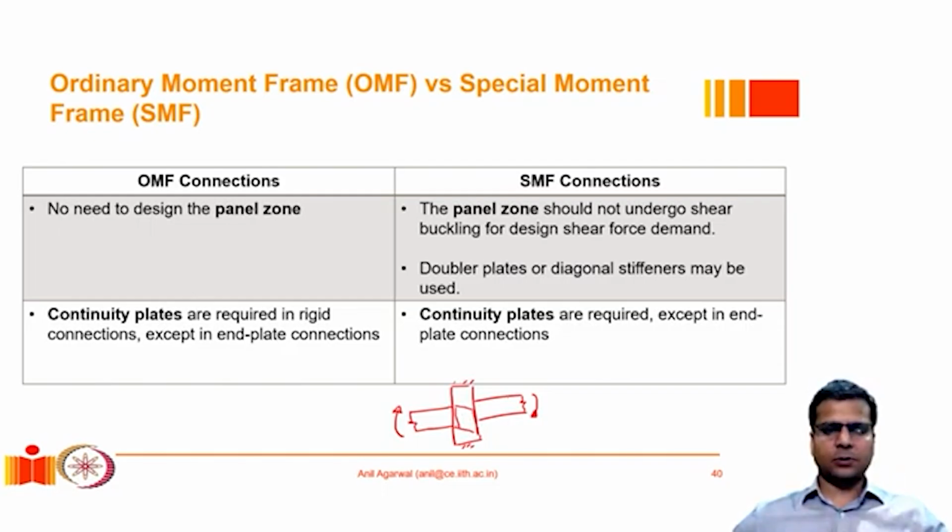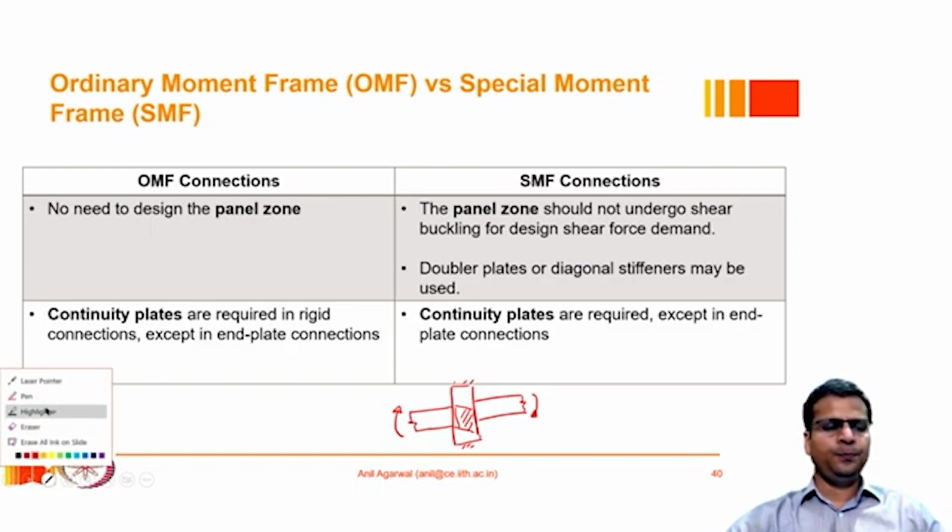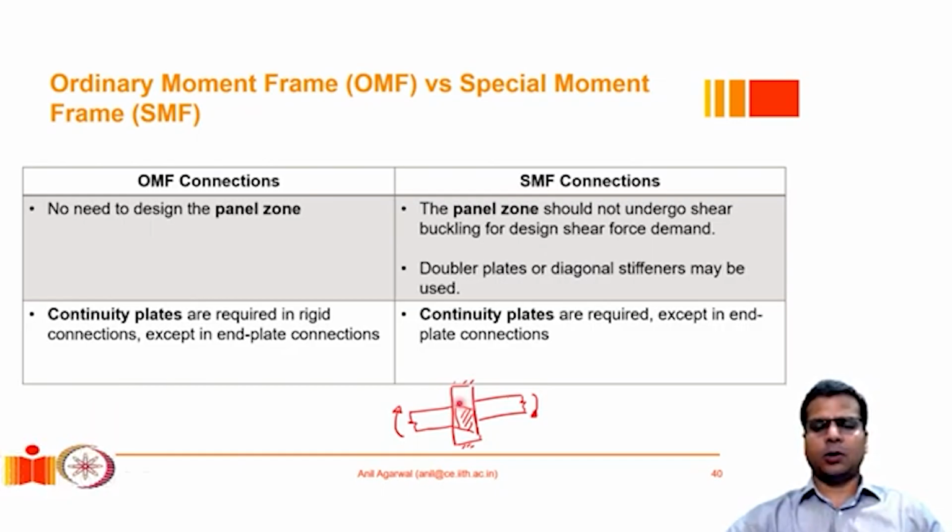And that shear panel zone will be a shear panel developing in the column web, which is generally considered to be very ductile in nature because it is governed by shear yielding of the column web. However, if the column cross-section plasticizes significantly, that can lead to an overall instability. So there are a couple of requirements corresponding to the performance of such shear panels.